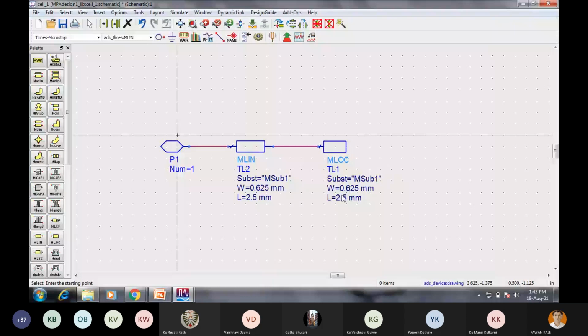Now what will be the length and width? Listen, it depends upon what kind of frequencies you want to design your antenna for. It depends upon the frequency at which your antenna is resonating. Accordingly, the length and width parameters will vary. And not just frequency, there are many more parameters which decide the length and width of the microstrip patch antenna. Right now I am not going to tell you how to choose the values of length and width.